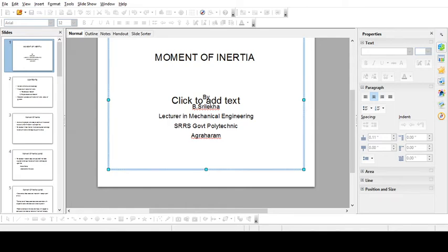Next, the major centroid. The major centroid is simply the centroid of the entire section. By making use of that, you can find the distance between the centroid of each section and the major centroid. That difference is nothing but the distance between the centroidal axes. Like that we'll calculate everything, and we'll calculate the summation of all the terms.